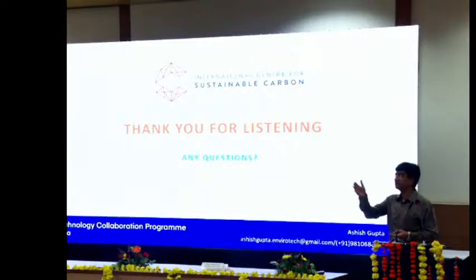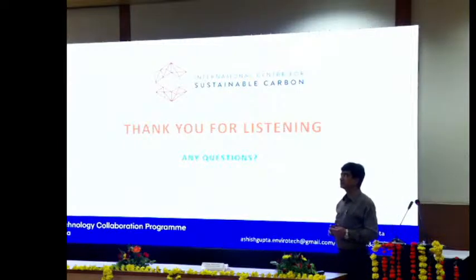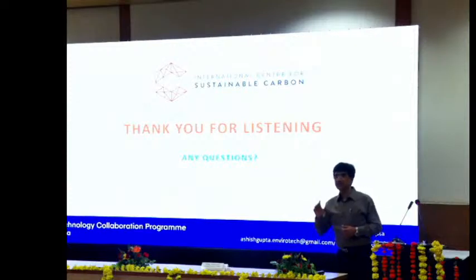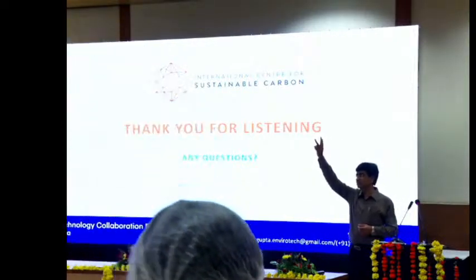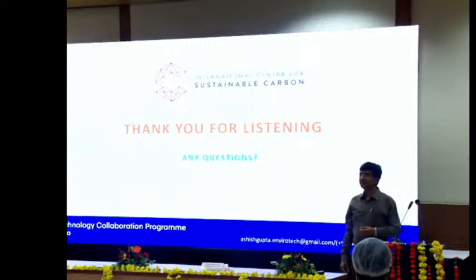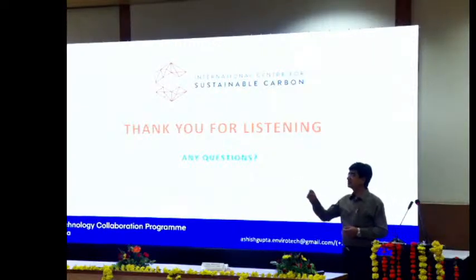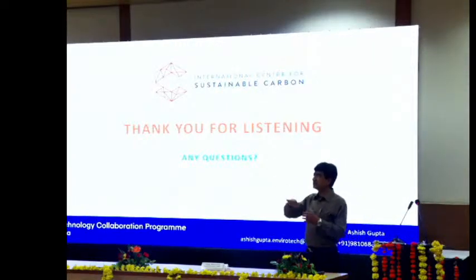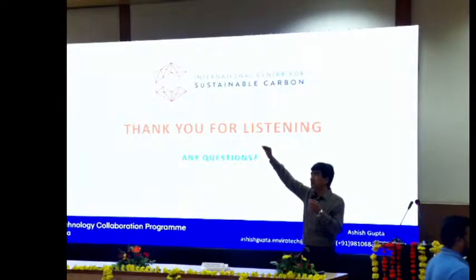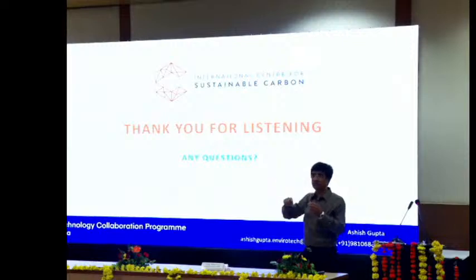Any other question? Yes, sir. See, that's very right. Why do we need 3 points? Anybody? Yes. See, in order to check the linearity, suppose you are making a reading at 0 and getting 100% at the other end, at least you should have one more point somewhere in between, so that you are able to check this graph, whether it's linear or not. And that's why they always say 3 point values.